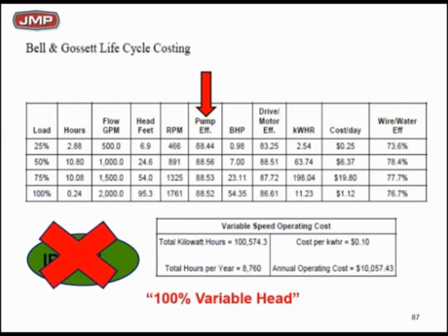We loaded in 10 cents a kW and the low profile we just talked about, and we went to the owner and said, your annual operating cost with this variable speed drive is going to be $10,000. $10,000 is going to be your cost. Here's proof. Here's the load profile. That is what you're going to get. We even went to the right-hand side and plugged in the wire-to-water efficiency for the motor and variable speed drive. We all know that's wrong, but that's what was promised to the owner.